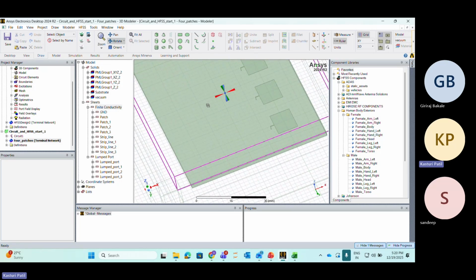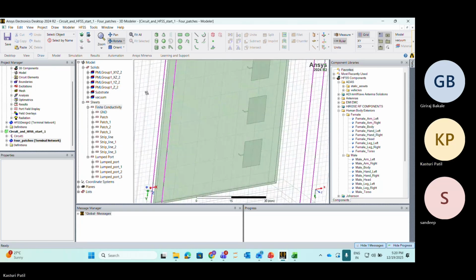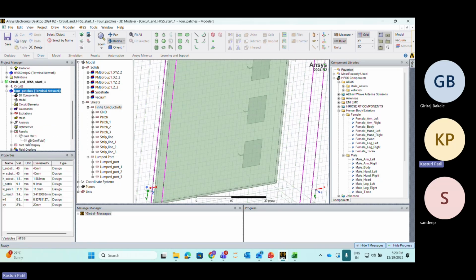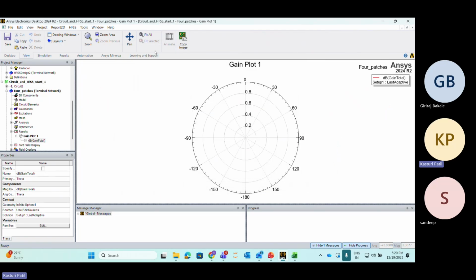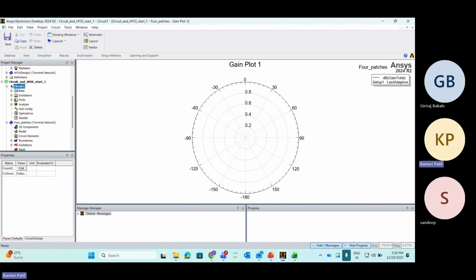Here we will see how to define an EM sub design in a circuit and set up its analysis. Second, we'll see how to link HFSS and circuit design. And third, we'll see push excitations. Basically, we have already designed the model in HFSS, and it is not working exactly at the expected return loss, so we can make changes, or we can match the circuit using ANSYS Electronics.